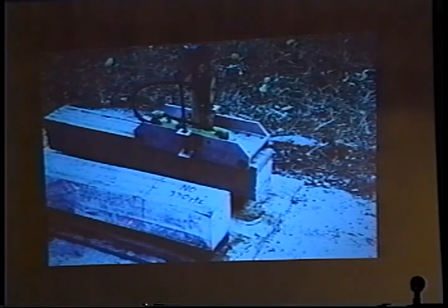So you notice this first beam, they broke it, it came up to 330. Well, it's not good enough. So then you wait another half an hour or an hour, you break it again. Okay, this will tell you when you can open it to traffic. Again, it's not rocket science, nothing high-tech here. Just a three-point load until you pump that thing up until it breaks the beam.